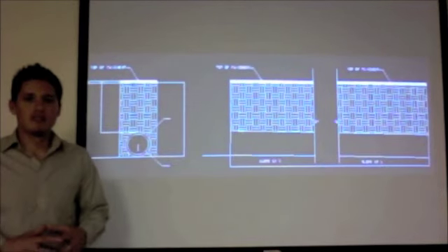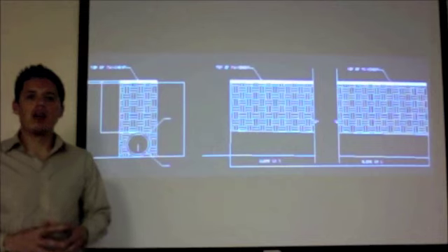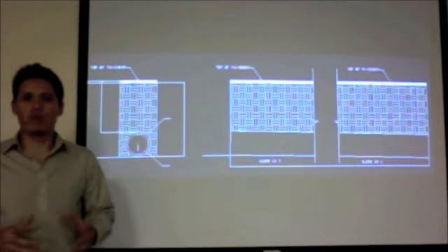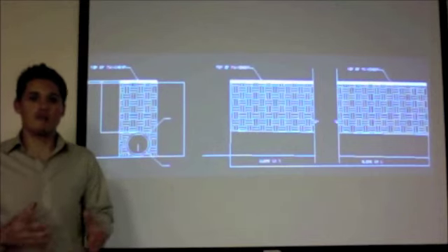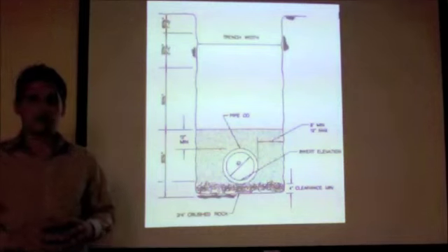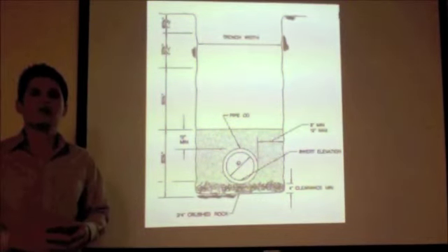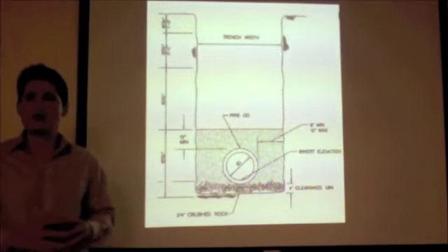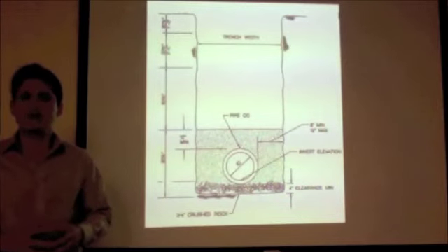Drain pipes. For the truss blocks, should have an allowable bearing of 2,000 pounds per square feet, a passive pressure of 350 pounds per square feet of embedment, a coefficient of friction of 0.35. Pipe bedding. As a minimum, the pipe should be supported on at least 4 inches of granular soil bedding material, such as 3/4 inch crushed rock.